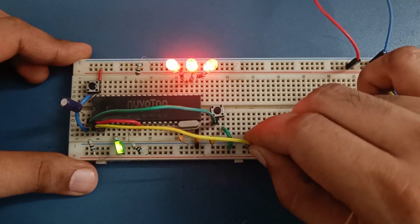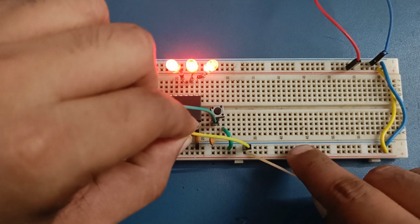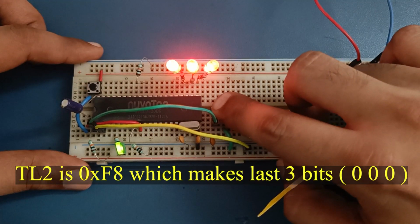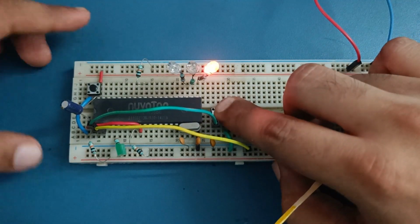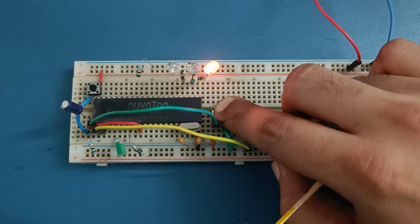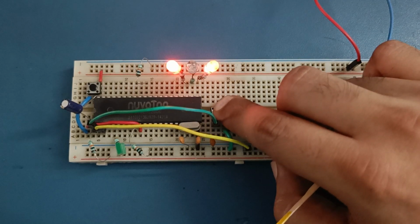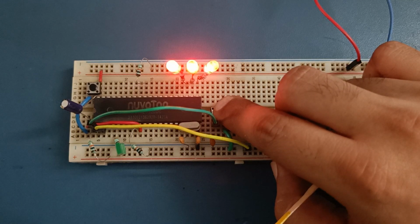Now I will use it as a down counter. So I have connected T2EX to 0. On the next count, this is 0, 0, 0, 0. It will become FFFF. So this is 6, 5, 4, 3, 2, 1, then 0.